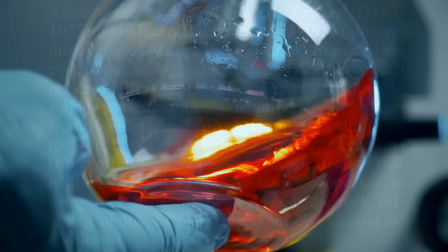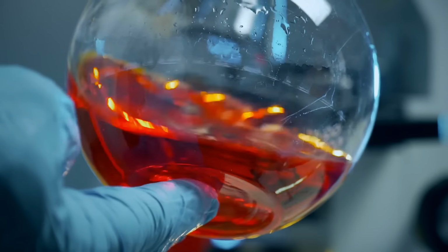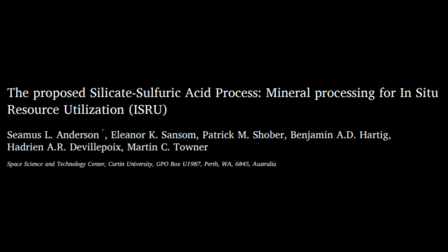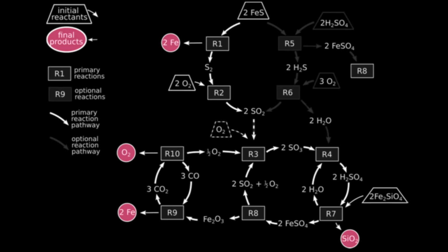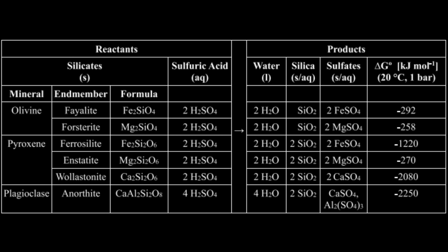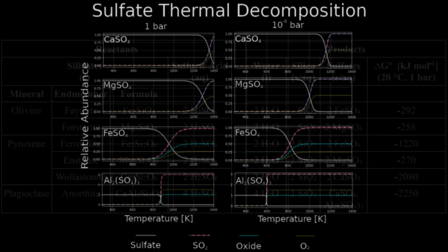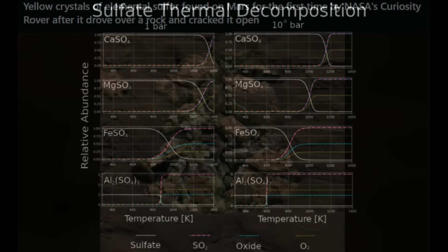Because of this rock melting stuff, sulfuric acid has a long history of use in the mining industry, especially for copper and uranium, and has even been investigated as a possible way to refine lunar regolith, with one advantage of this approach being that it would require lower temperatures, peaking at about 900 degrees Celsius, but this temperature would not need to be maintained for the entire time. It's just the maximum temperature used in this entire process at one point in the process.